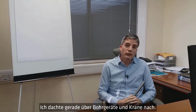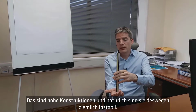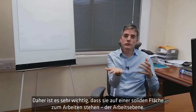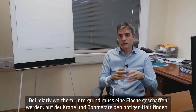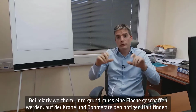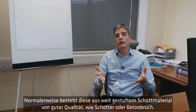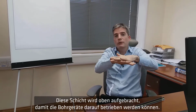So I was thinking about piling rigs and cranes. They are tall structures and of course by their very nature are rather unstable. So it's very important that they have a strong platform from which to work, a working platform. On ground that is relatively weak, that means you need to construct a platform over that weak ground to provide sufficient support to cranes and piling rigs. That's normally composed of a good quality, well-graded granular material such as a crushed rock or crushed concrete. So you place that layer on the top on which the piling rigs and cranes can operate.